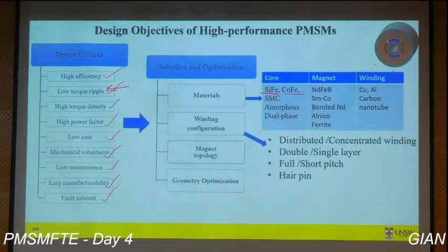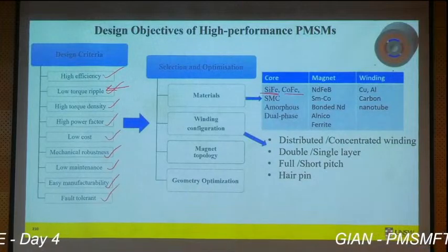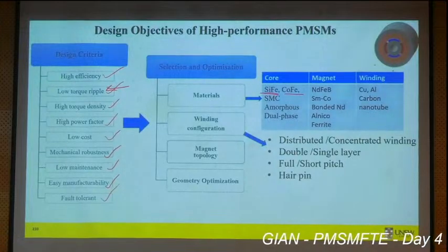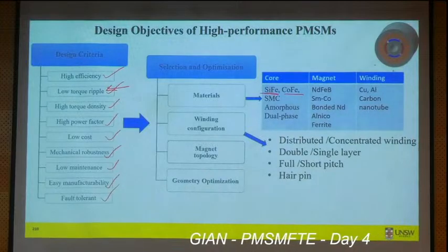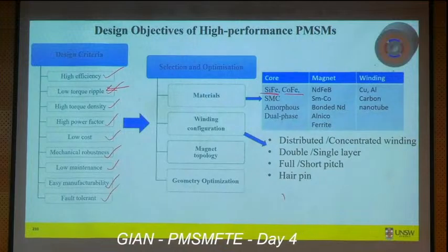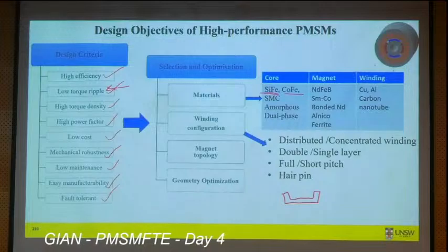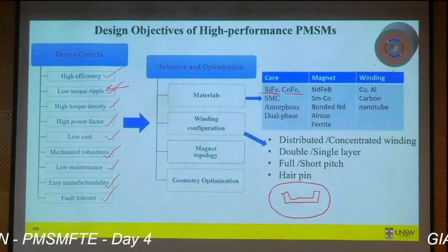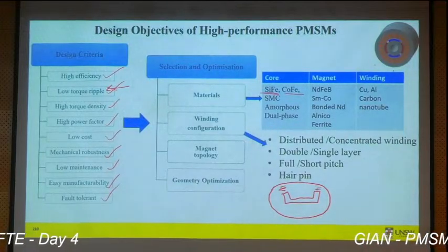Similarly, dual phase material. The dual phase material is such that part of this material can become non-magnetic and other part can remain magnetic. So this dual phase material could be very useful while designing either the IPMSM or the synchronous reluctance machine. So in synchronous reluctance and IPM machine, this part is usually highly saturated.